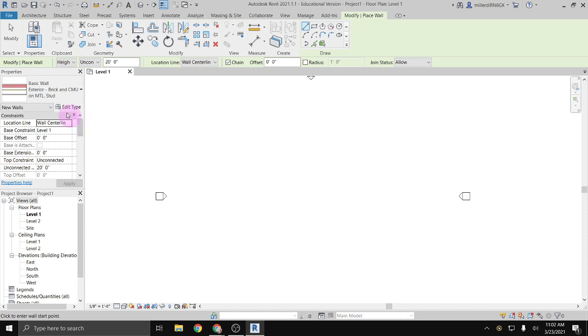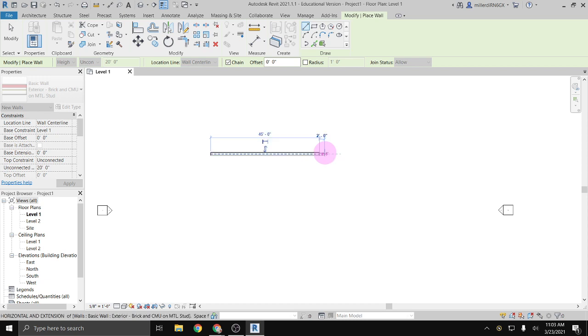And so I'll just start placing a wall down. I'll just click where I want the wall to start, move my cursor in the direction I want to go, type the distance I want, enter. Nice thing about Revit is because we're using an imperial template and because it's an architecture software, Revit knows I am thinking feet and inches. So I no longer have to type in those designators. If I just type in 12, enter, it's going to assume 12 feet before 12 inches, unlike AutoCAD did.